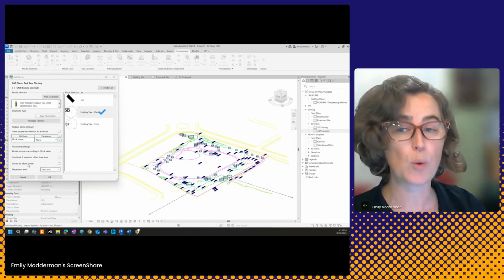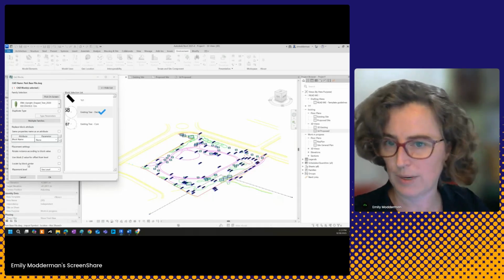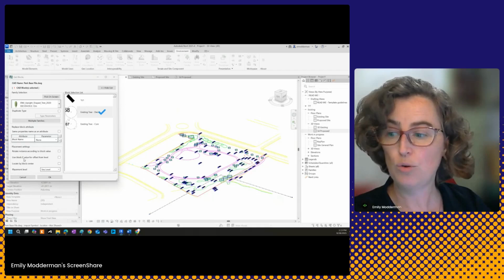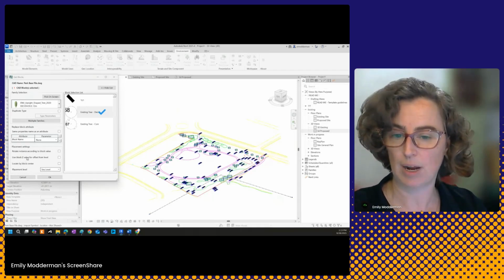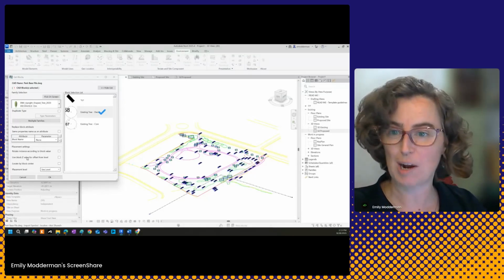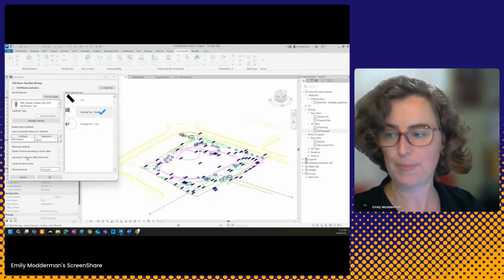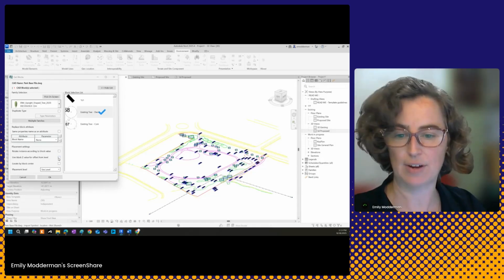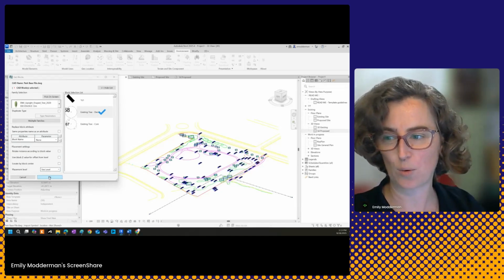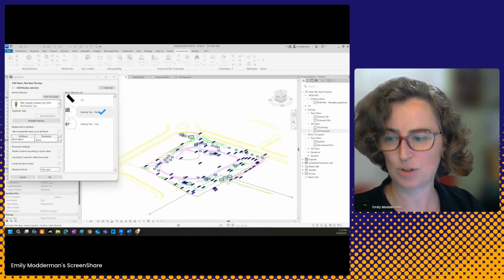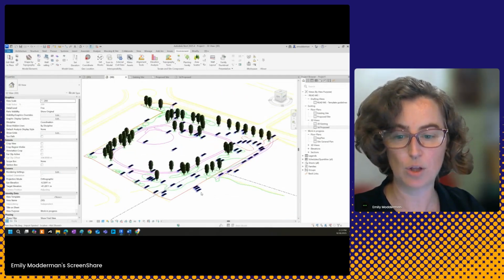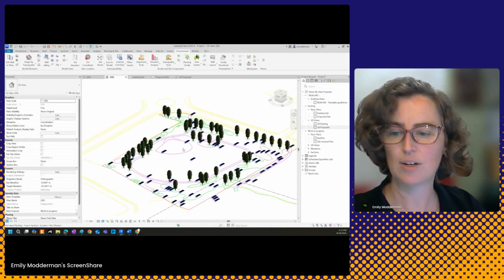And we can do things like locate by block center, right? So we get the same center of the block location and the family. Use Z value. So if you do get a CAD file with a 3D elevation, where your blocks are up at an elevation, that's super, first of all, and so you can use that Z value. Minus flat, nothing to use there. So I'm just going to click OK now that I've mapped my CAD to my Revit. All right, look at that. In the blink of an eye, I have a lot of trees in Revit format.